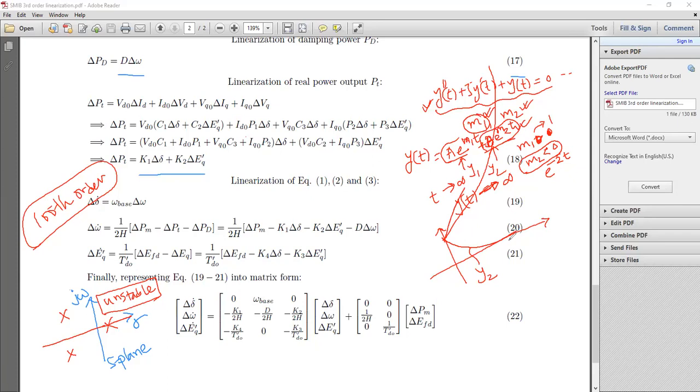The resultant would be, although the first one, that is y2, is decaying, the resulting value would go to infinity. This is why even a single positive pole, even a single positive root, for a dynamic system is enough to give you an unstable or unbounded response.